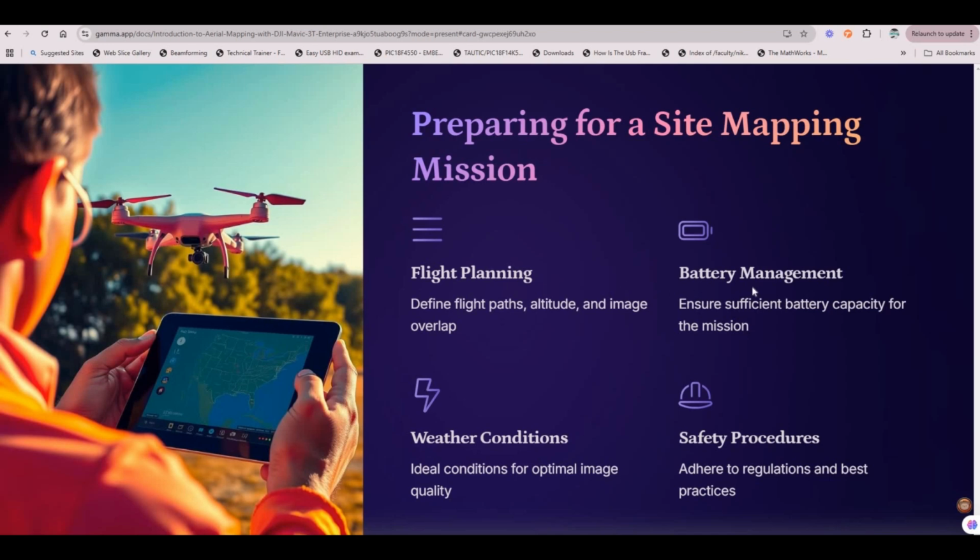And then before you fly, these are some of the rules whenever you fly the drone. You need to check the battery. So on this particular drone, whenever you want to check the battery, you can just press once, and you can see how many lights. So this is full. Likewise, you can click at the back of the drone. So you can see it's full, 4. So this battery is important because you always have to check the percentage of battery when you're flying a drone.